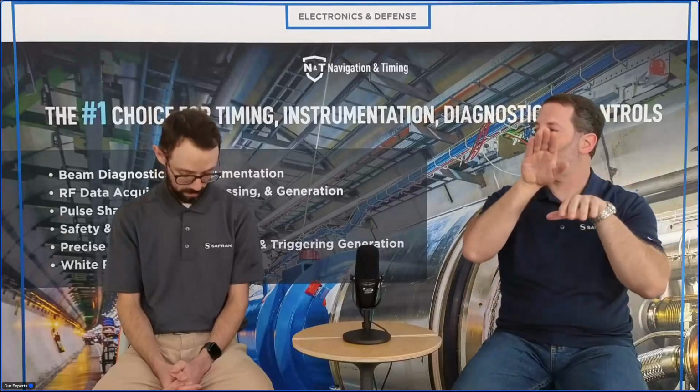That's what we do for synchronization, right? And as part of that, obviously we are adjusting the frequency of the oscillator to track the input. And so we are purposely setting the frequency off, not by a lot, but enough to steer. And so when you go into holdover, we have to bring it to what we believe is the real value in order to kind of maintain where we are for as long as possible. And so there's a learning period for that in order to do that.